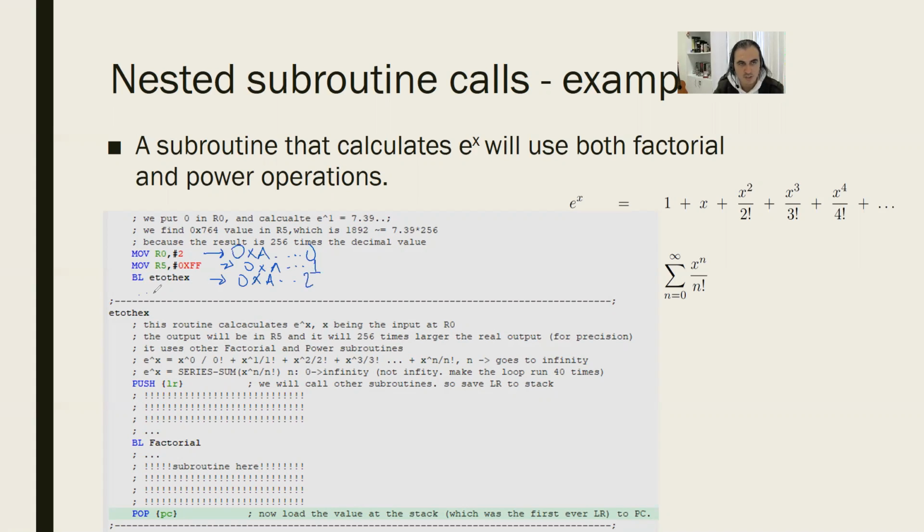And there's another code here, and that should be at line 3. So guys, when you do BL, what happened was there was the LR. When you executed this, the LR value was set to the next execution code, which is 3, so that when I come back, it was going to be overwritten. Okay? So I use BL inside as well. So if I use BL, this value will be lost.